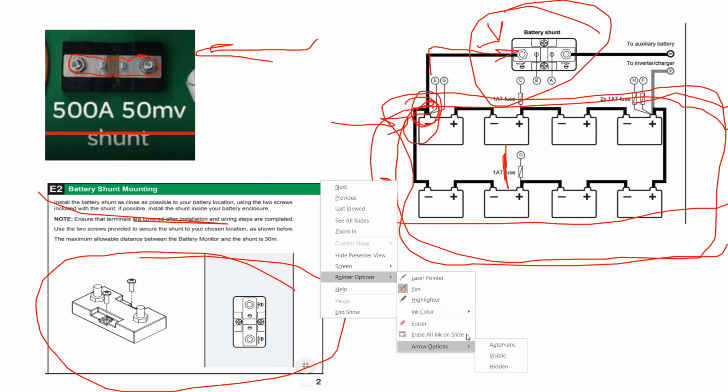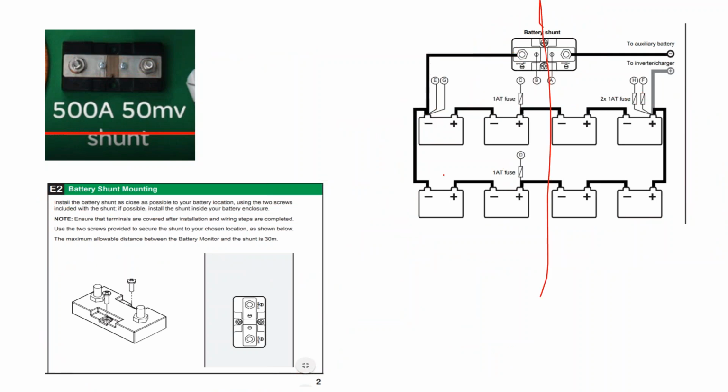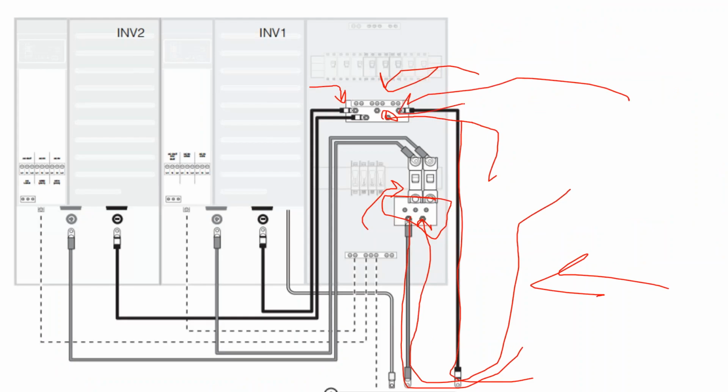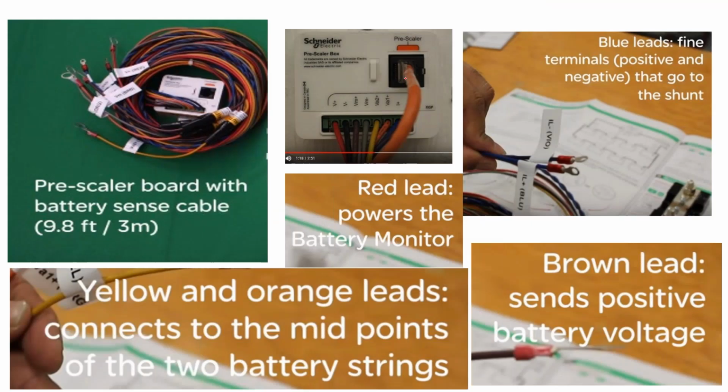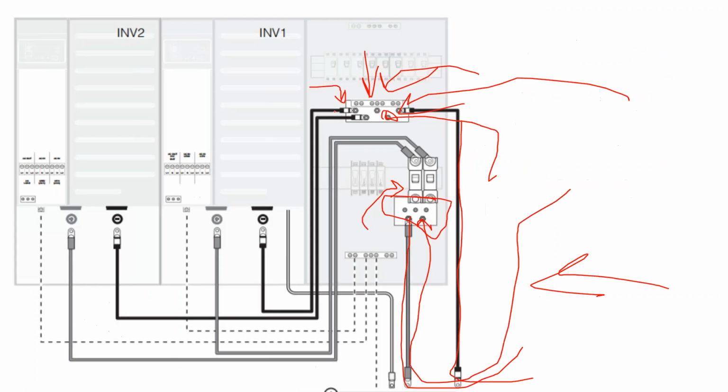We're taking our 2 circuits of batteries and then running them directly back to this bus. So there's actually no location, where our parallel wiring is occurring right here, for us to put the shunt in line before we run back to our inverters.